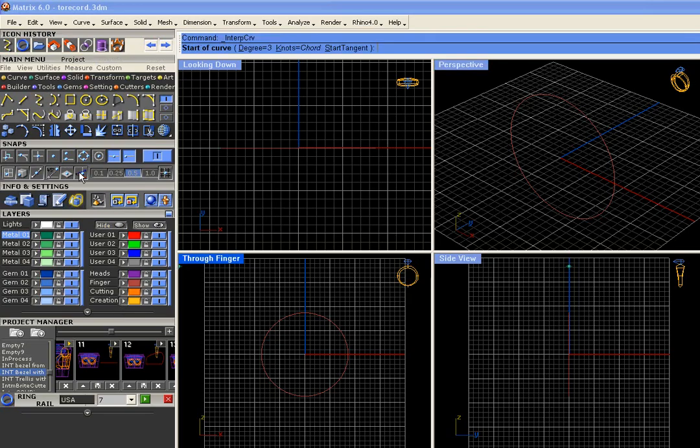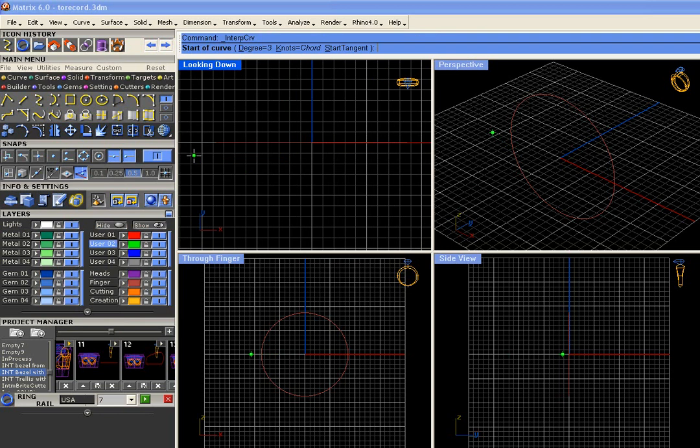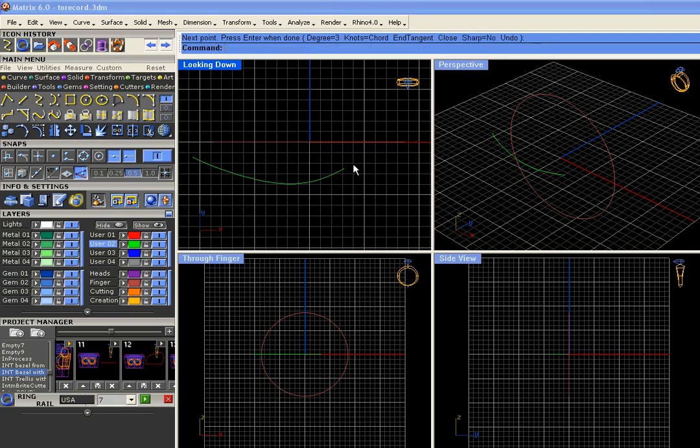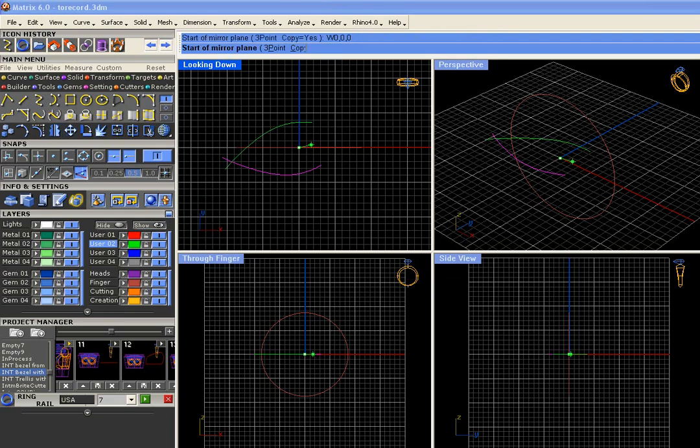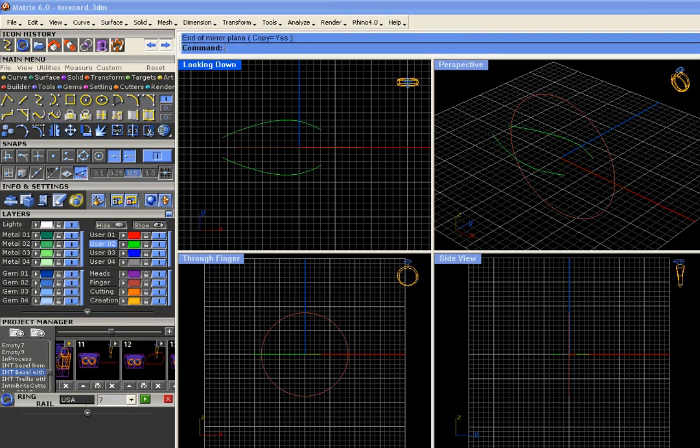and turn on project. We're going to go ahead and draw this and kind of center it at the thickness you want for the ring. Okay, you can pass F4 there. And then we'll mirror this, and I'm going to go ahead and mirror it with Rhino history turned on. This will just give you a little lesson in history. Okay, mirror this around F4, holding down Shift.